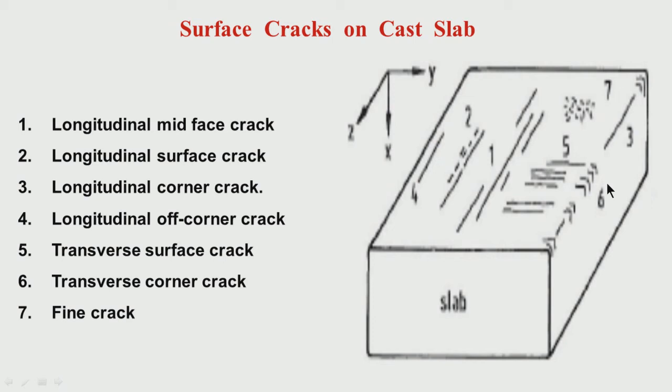So, it is towards the cast front, that means it is transverse in nature. So, if the stress is transverse in nature, you may have a longitudinal crack. That is why what I am mentioning is the possibility of having longitudinal crack is there when the casting is just taking place in the mold, because these have formed mostly in the mold area.